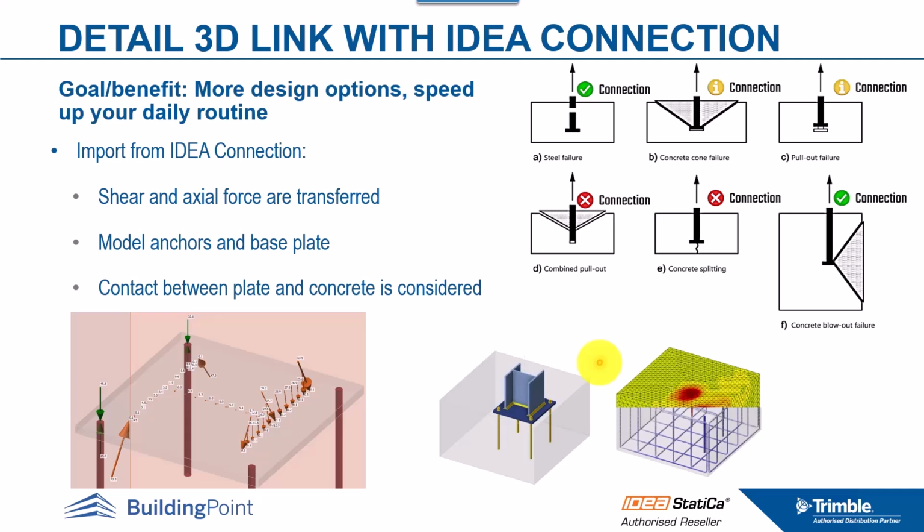Once we are thinking about the design of the steel, we are mainly thinking about the operations, about checking the bolts, welds, the plates, end plate, cleat plate, fin plate. So we are thinking about the operation design. The main member will just be designed in general FE solutions like SpaceGass or ETABS. But for the connection design, we have the operations, as we said, like bolts, welds, end plates, cleats, fin plates, gusset plates. Those kinds of operations can be design checked in IDEA StatiCa Connection.